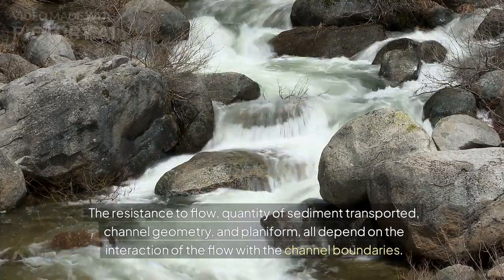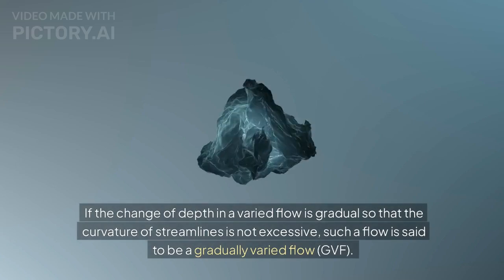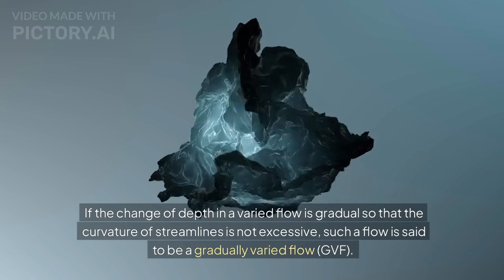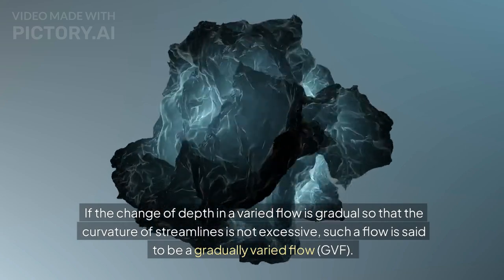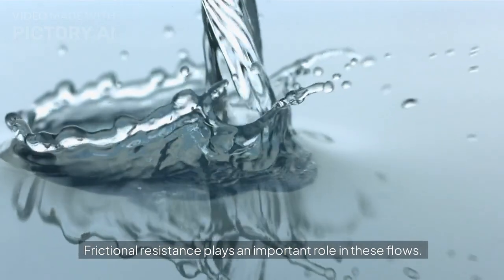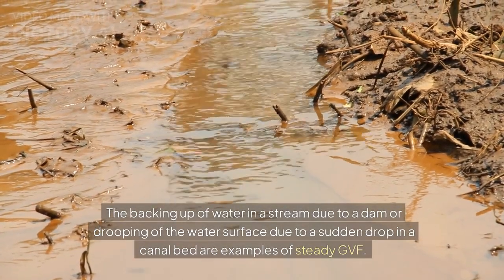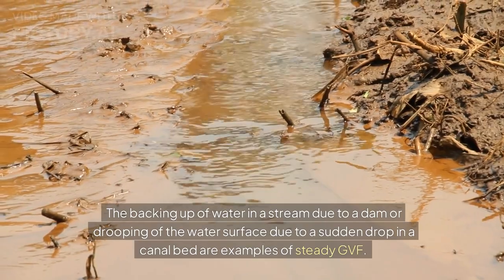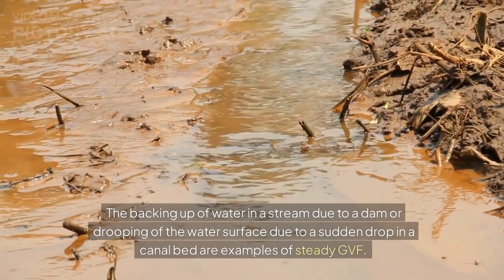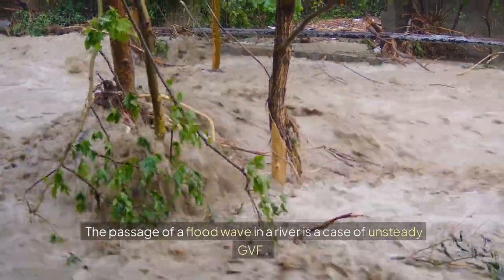If the change of depth in a varied flow is gradual so that the curvature of streamlines is not excessive, such a flow is said to be a gradually varied flow, GVF. Frictional resistance plays an important role in these flows. The backing up of water in a stream due to a dam, or drooping of the water surface due to a sudden drop in a canal bed, are examples of steady GVF. The passage of a flood wave in a river is a case of unsteady GVF.